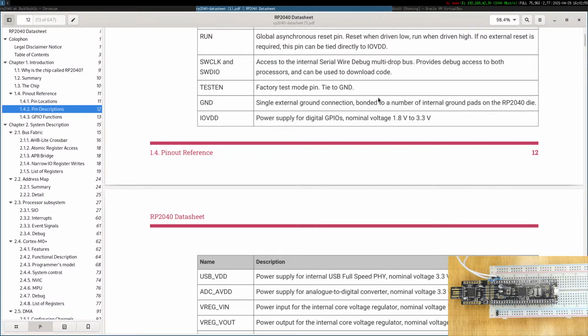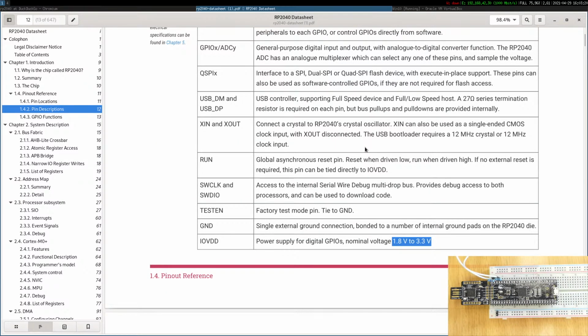So no, don't try to convince me that the new RP2040 is a messiah and can solve all my problems. It doesn't fit the things I want. I cannot do analog on all the channels, and even if I had an external multiplexer, I cannot do 5.5 volt IOs, which I want to do.